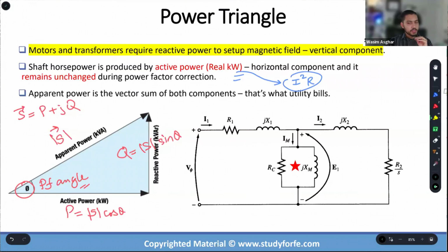Even the cables have inductive components. Transformers and motors have impedances that are almost completely inductive in nature. And for cables over large distances, the series inductance of the cables and transmission lines becomes very significant.